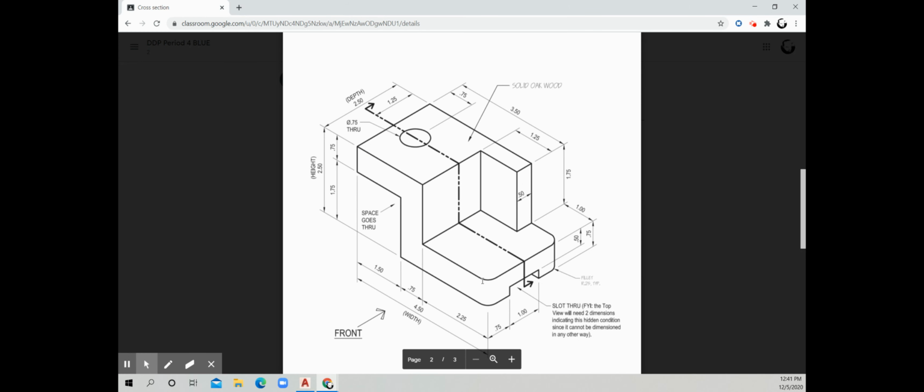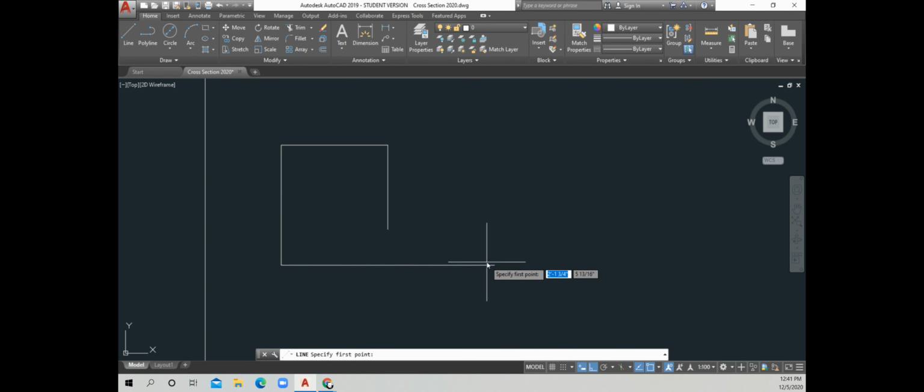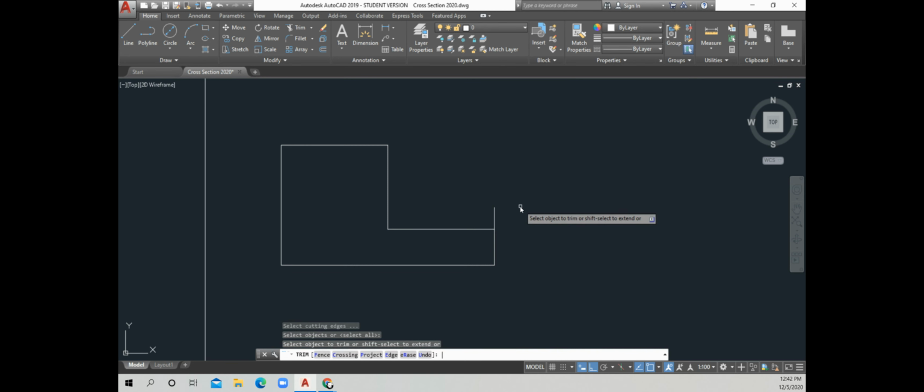Now remember, I said this is a radius, but it's going to be a straight line. So we merely need to match up the edge of this line. So why don't we do my old technique of more than you need here. Let's draw a line here, bring it right up to it. Let's trim off the extra. Just like that, and we save.